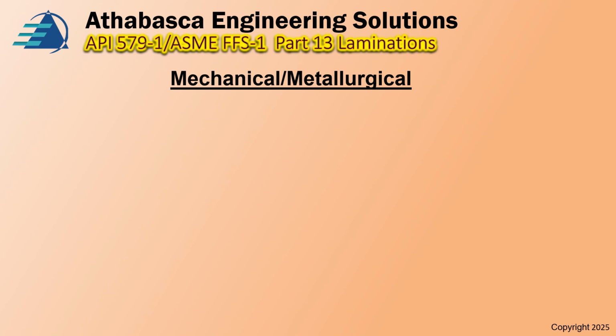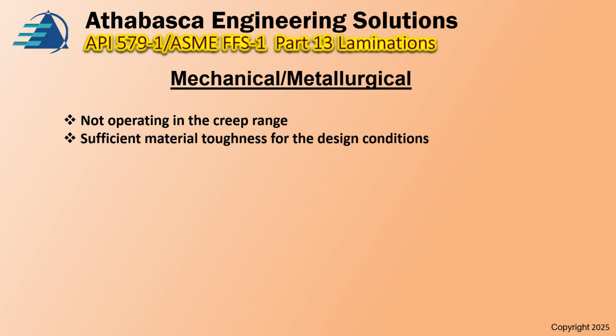Mechanical and metallurgical aspects of this design: we determined that the system is not in the creep range, so we don't have to revert to the part on creep for this assessment. We have sufficient material toughness for the design conditions, which for all the parts you have to initially check to see whether you have a brittle fracture issue or not, for all the conditions including the hydro testing.